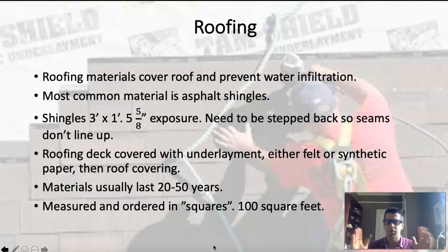Okay, so let's say the front of the house is 30 feet. Half of that, this is some roof framing terminology here, the run is going to be 15 feet. And then if you know what the pitch is and you get the diagonal, then that's going to be one length of the roof as well. Okay, so it's not going to be 44 by 15. 15 is the run on a 5 and 12 pitch or whatever the pitch may be. You would determine the diagonal of that, and then that's how you would measure up that roofing. Okay, but that's maybe a discussion for another time.